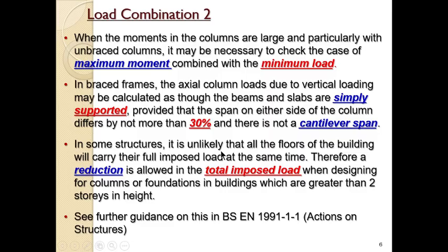So, still on load combination. Now when the moments in the columns are large, and particularly with an unbraced column, it may be necessary to check the case of maximum moment combined with the minimum load. So there are times you want to say, okay, what is the maximum moment that this will carry? Let's combine it with the minimum load and see the effect that it will create.